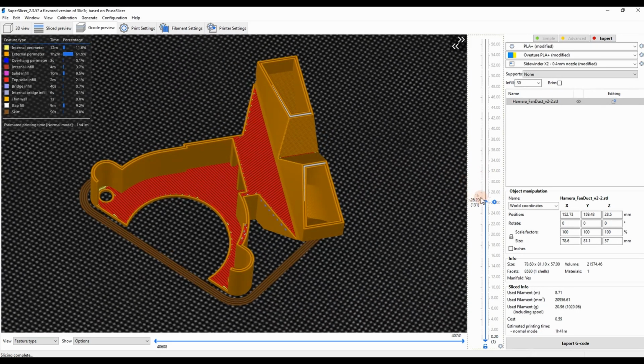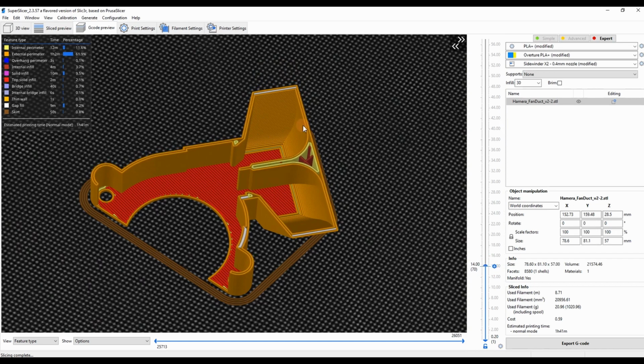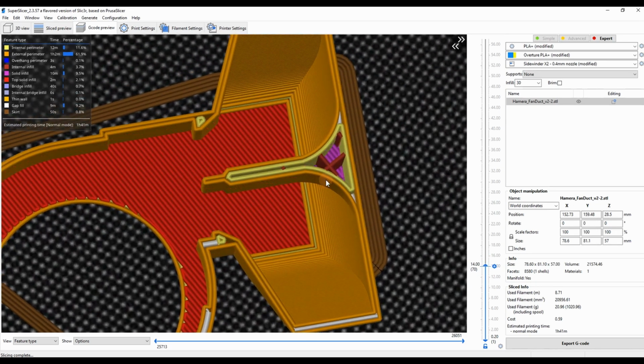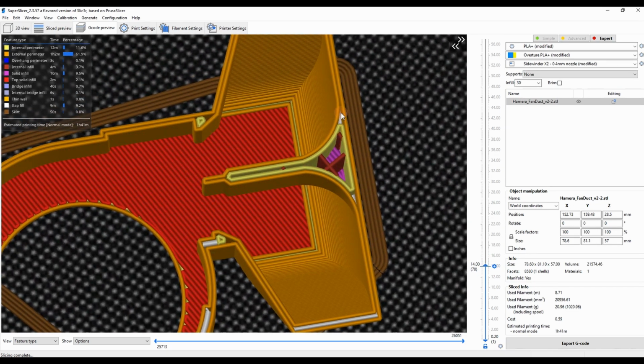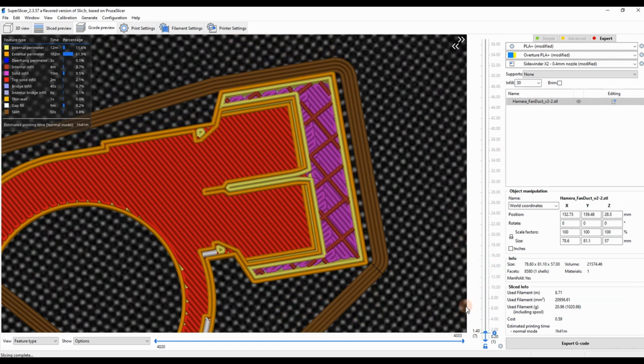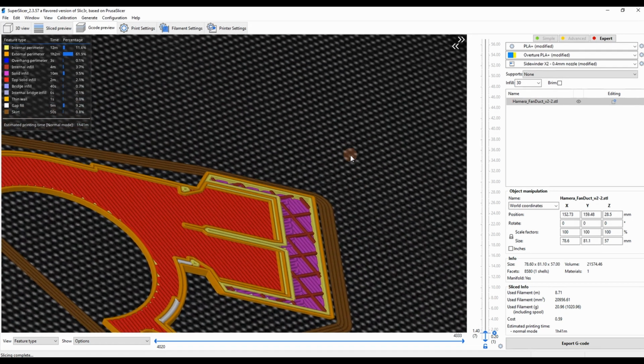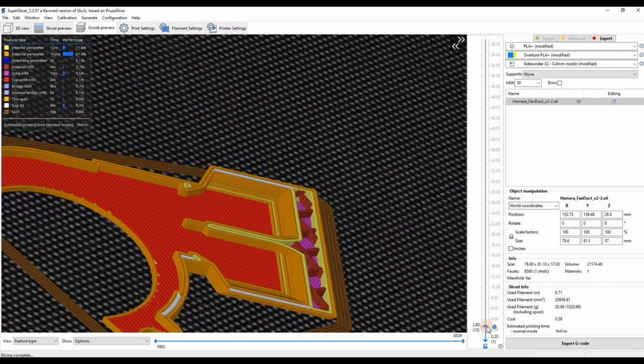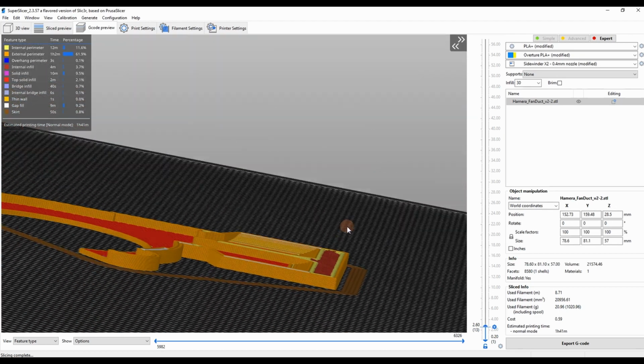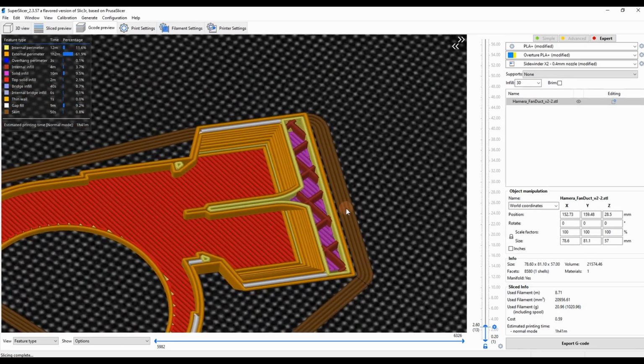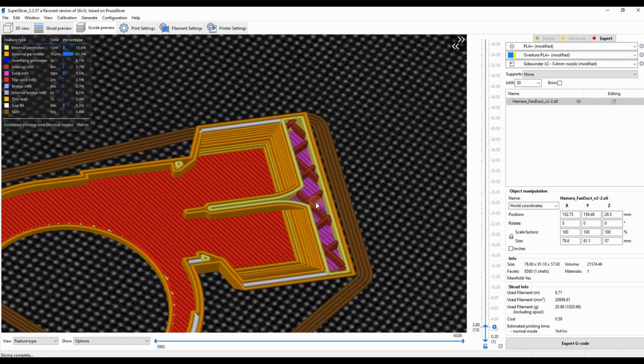And then internal infill. So this is any space within a body that your perimeters don't fill up. You can tell it what style and what density of infill, and that's what this red grid pattern is here. This is where the names on the Lemon Lattice website come from. The grid, the honeycomb, and the gyroid, those are all infill patterns.